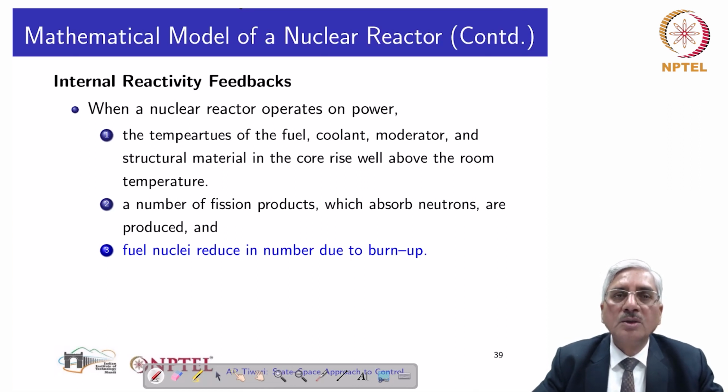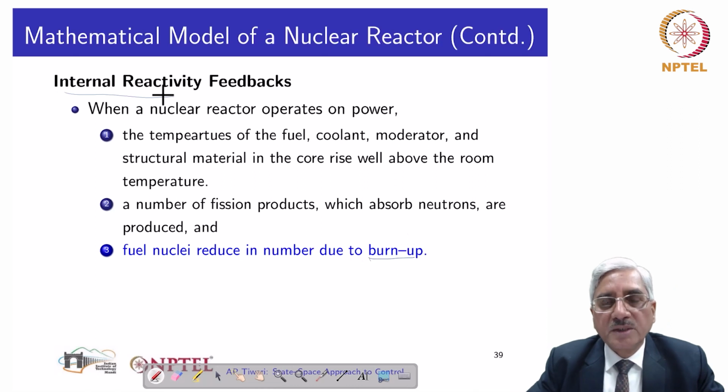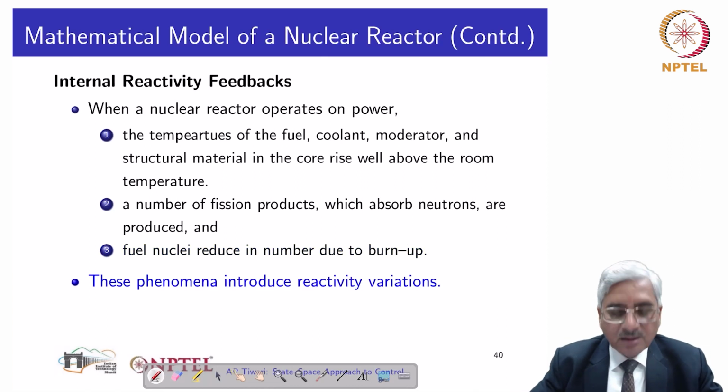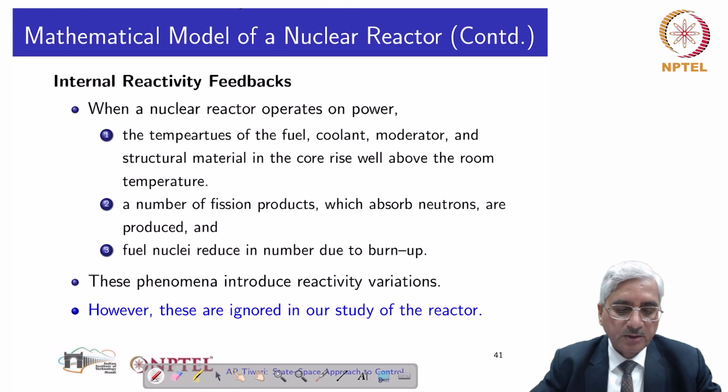Even though it is slow, and even though refueling is done to bring back the fuel loading to equilibrium, nevertheless there is always a burn up of fuel and an internal reactivity feedback because of that. All these phenomena are there, but we are not considering them. They introduce reactivity variations, but we are ignoring these phenomena.